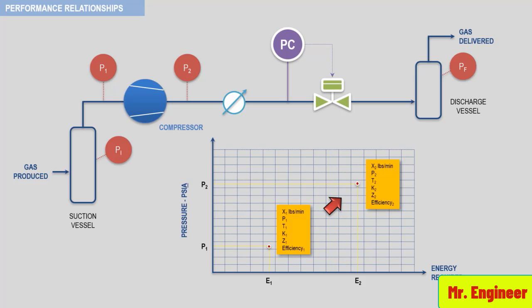The vendor then determines the head required by the process based on the parameters given by the end user on the equipment data sheet. It is very important to note that all possible sources should be used to confirm that the conditions stated on the data sheet are correct and realistic. This fact is especially true for dynamic compressors, since incorrect process conditions will impact the throughput of the compressor.